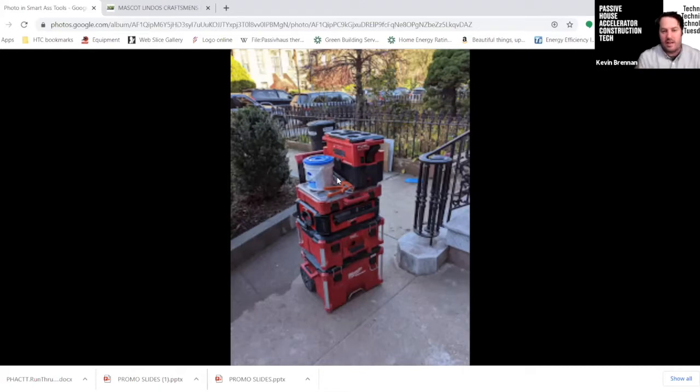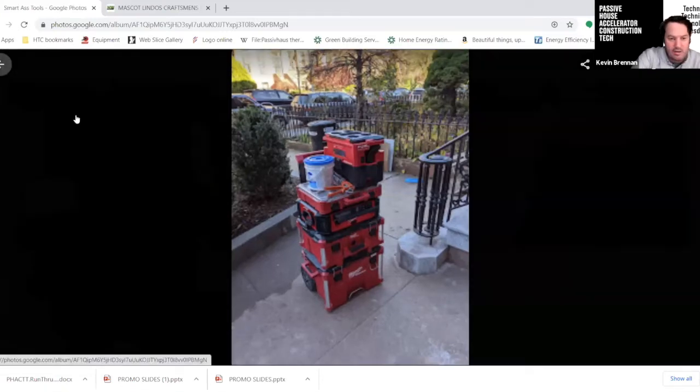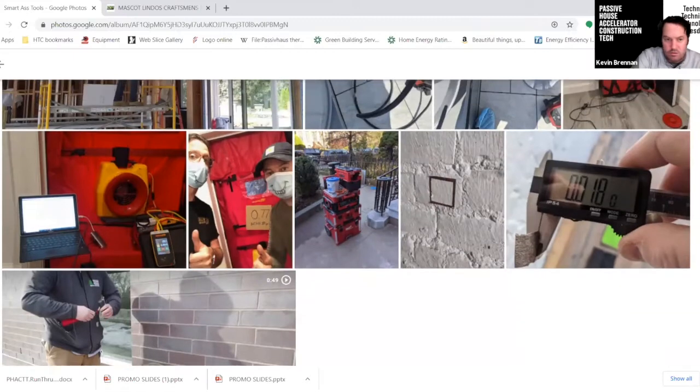So I wipe it, I clean it. I'm doing my white glove test to see if the surface is clean. I wipe again. If it's clean, then I'll let it dry, which should take around 10 to 30 seconds as I'm cutting my tape, and then I'll press it. So we'll back out of here. I'll show you my next step.